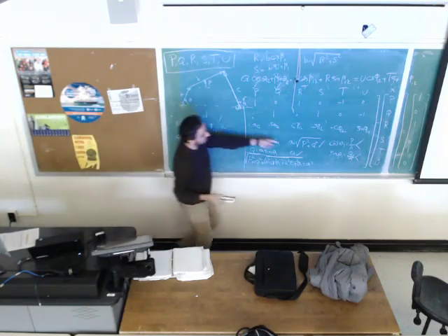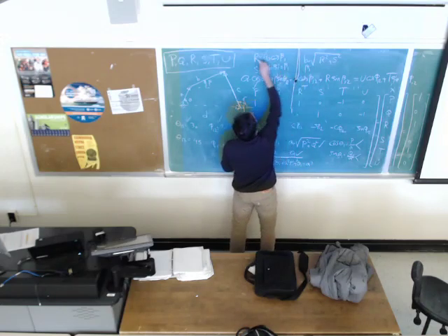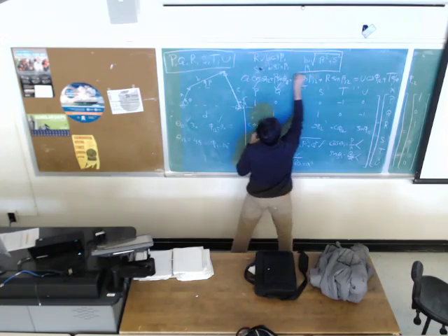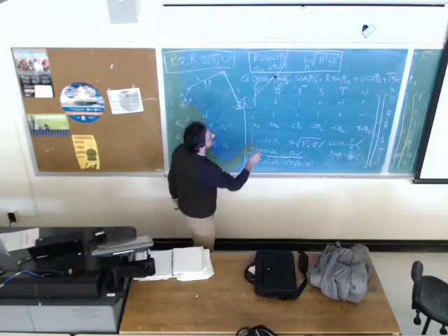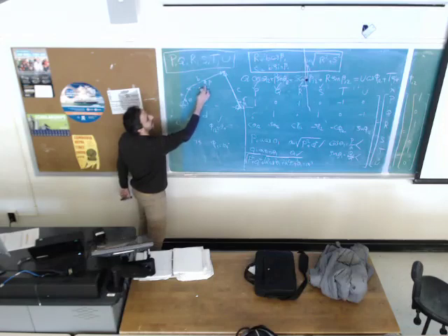You find B with the same method, find beta 1. This is R and S. So you find the length of B and the angle of link 3 at the first precision point, which is beta 1.